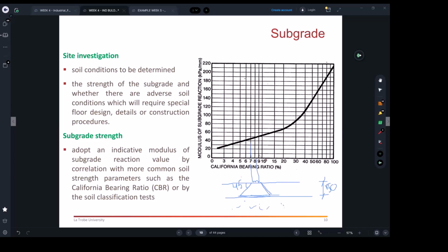And if he gives you a figure, you will be able to know the maximum kPa pressure a soil can take. That will give you 1 millimeter. And the standards on the other side will tell you how many millimeters you are allowed to settle a soil. That's how simple it is. Okay. Any question?